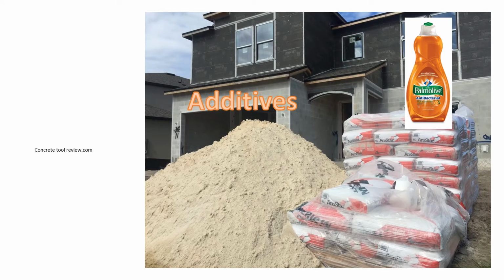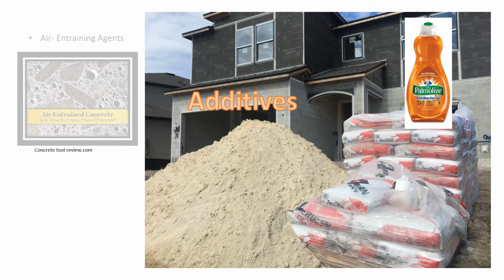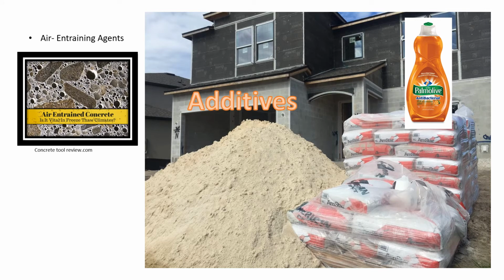Additives and admixtures can impart unique qualities to cement base coats. They can also ruin them. Caution should be exercised when adding any additive to a common lime cement mix. Blended or proprietary products must get approval from the manufacturers. A prime example is the additive known as air entraining agents. These agents can make cement more workable by adding tiny air bubbles to the mix. They can also help with freeze-thaw issues by giving trace amounts of water a place to expand.